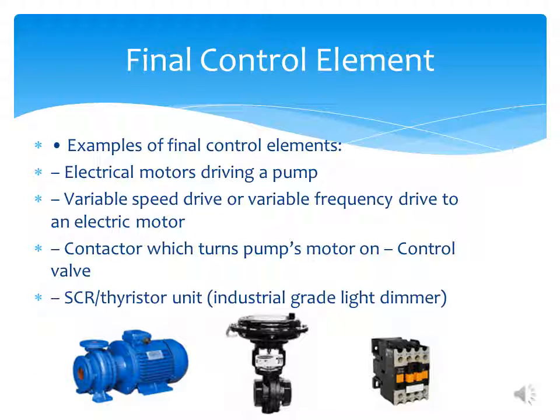Examples of final control elements: electric motors driving a pump, a variable speed drive or variable frequency drive to an electric motor, a contactor which turns the pump's motor on, a control valve, an SCR, a thyristor unit, an industrial grade light dimmer.